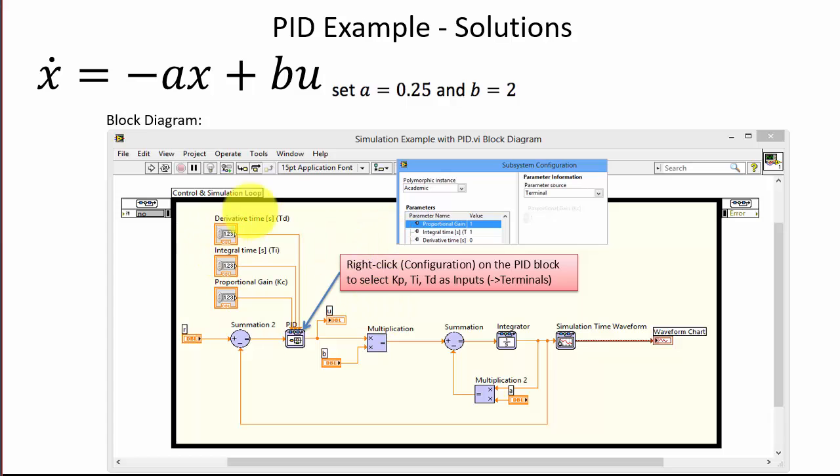So here we see the code we are going to create. This is the process we already created, so we need to replace the manual control signal with the PID block like this, and then we need to add a new summation point where the error between the reference and the process value is calculated and sent to the PID controller, and based on that the PID controller sends a proper control signal to our process.